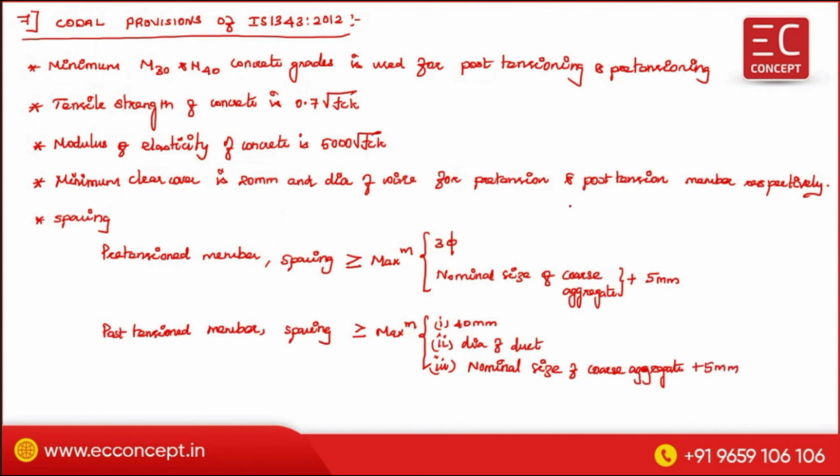Okay. Now, next point, diameter of ducts. Diameter of ducts is 2 to 2.5 times the diameter of wire. Okay. Next one is longitudinal reinforcement.